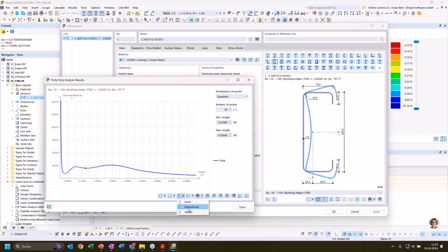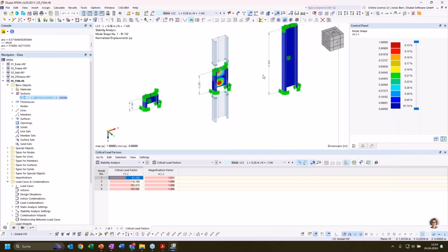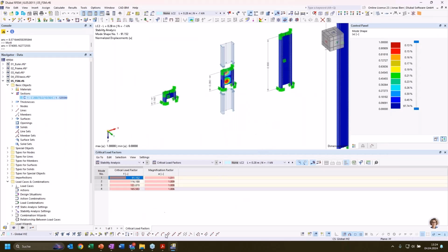And it also has a practical use. For cold-formed design within our steel design add-on, we use the distortional buckling curve evaluated on the basis of this finite strip method to evaluate the effective sections of our cold-formed section. So we directly use the second minimum of this distortional buckling curve in the design of cold-formed members according to Eurocode 3 part 1-3, and also for cold-formed design according to the American standard, the direct strength method. So it has a practical use and is already implemented in the cold-formed steel design. All right, that's it for the second topic, the cross-sectional design.